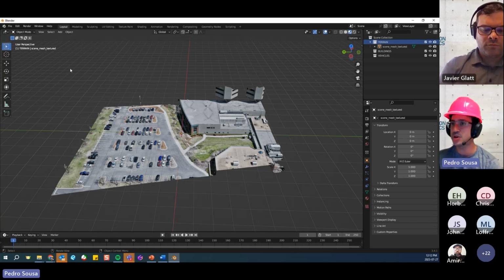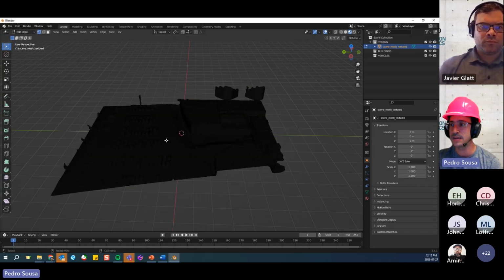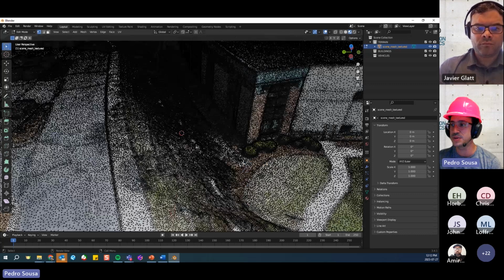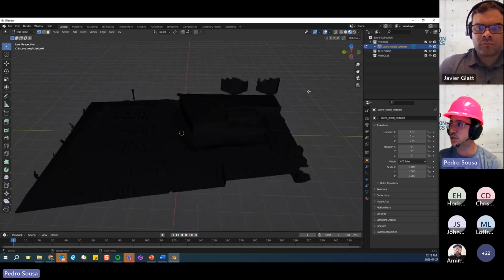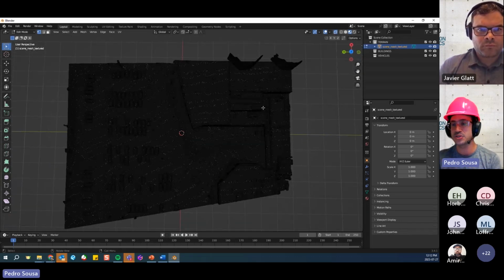To separate the geometry, we're going to click on that, and go into edit mode. This will expose all the vertices of that structure, as you see over here. We're also going to click on the X-ray selection, which is this button over here on the top. That means that every point that my selection touches will be selected.